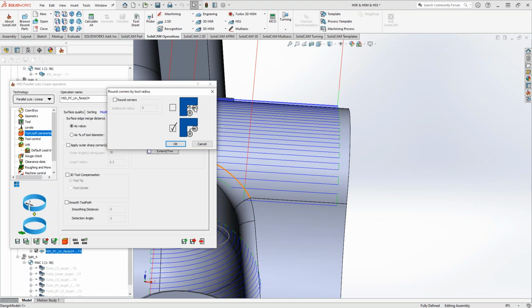So what the toolpath will do is it'll generate this kind of triangular motion to make sure it gets all kinds of contact points in there. But rather than do that, let's say we want it to just go in and come out, make its own corner, make a nice smooth 90-degree turn, not even trying to do this triangular motion. Well, if you check the box, that's what you get. That's basically what this is telling us.